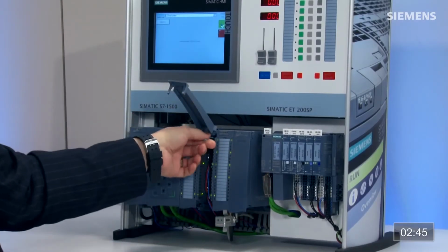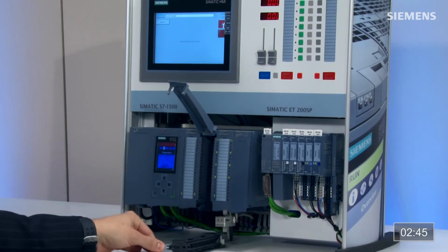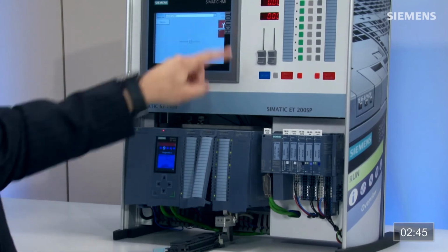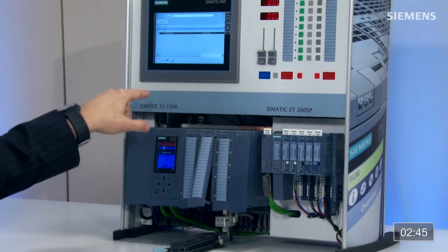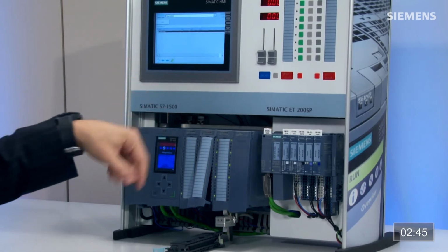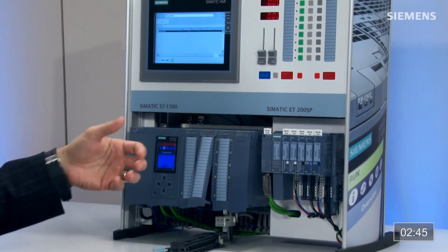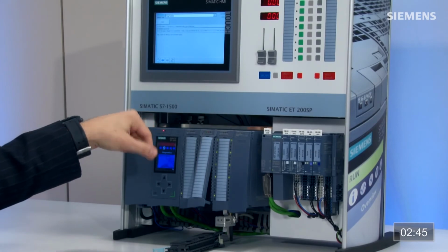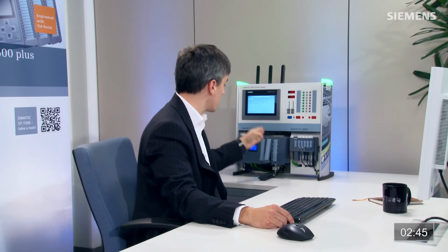Well, we can. If I come over to this card right here, if you remember I did no supply voltage for this one, and I pull it out, you see the diagnostic indicator on the HMI has turned red and there's a wrench now. If I click on that, I'll see I have some kind of message in this local hardware architecture. I can click on this button right here. It's going to generate the ring buffer and show all the diagnostic messages. No supply voltage, that is correct. Click on the plus sign over here to find physically what it is. It tells us exactly that there is no supply voltage, all the way down to the actual card in the rack and potentially how to solve the problem, including the part number, and not one line of code was required to achieve this. Now that is engineering efficiency.